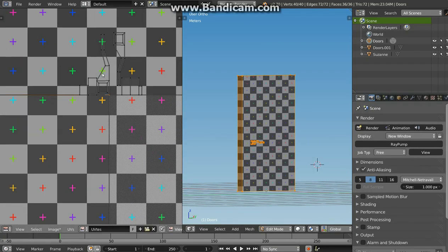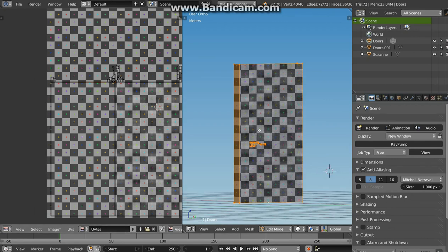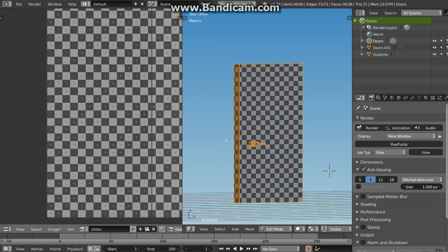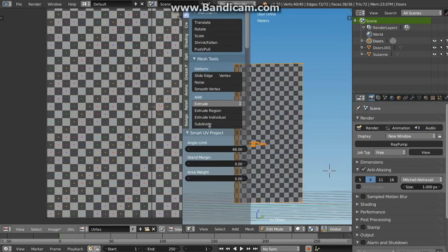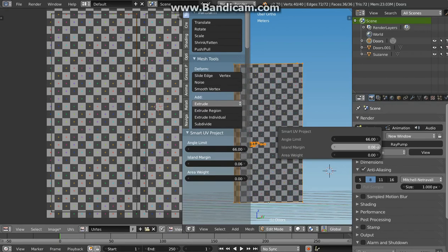So always when you have different islands, and you probably will have it always when you unwrap something, you want to set margin, and as with any function in Blender, after you apply it, like Smart UV Project, you have a chance to go to the tools, for example, and set the values for the projection, or with F6, and there is island margin.